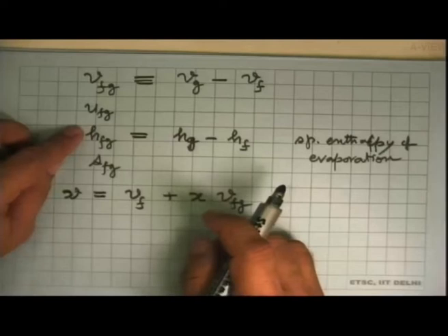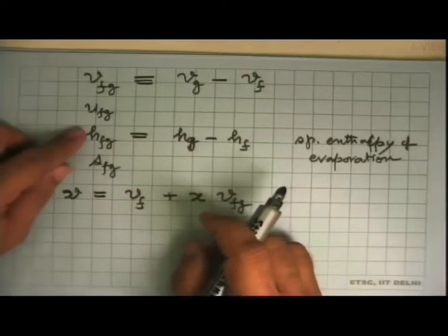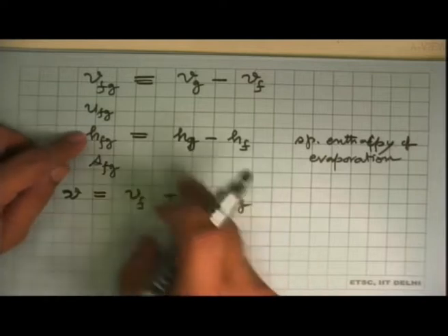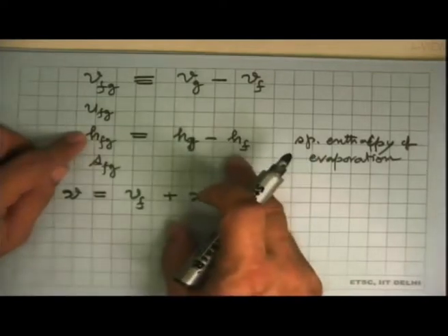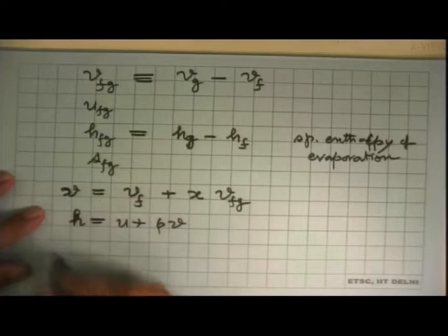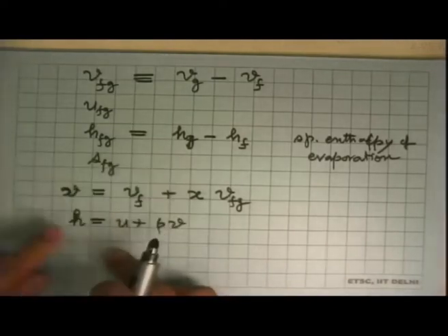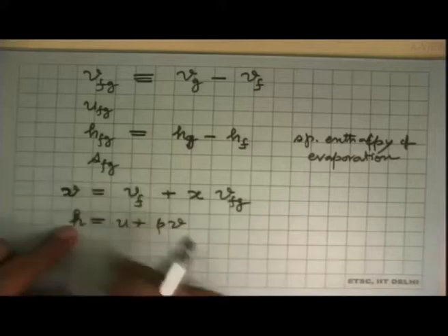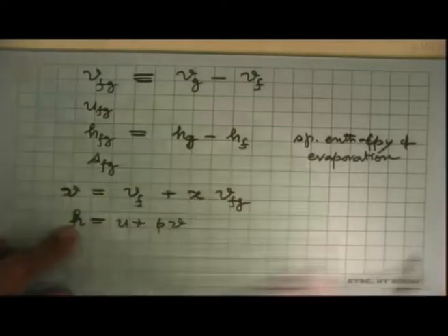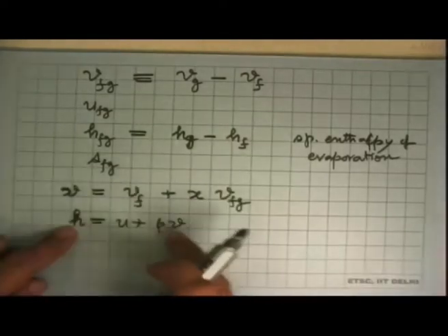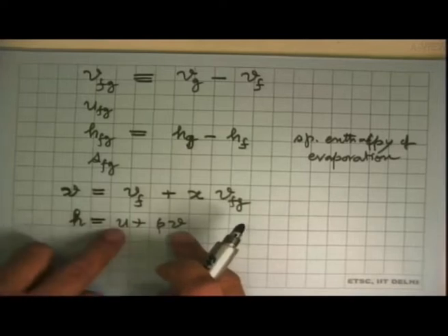Okay. In many cases, the tables will give values of these also, but there are many cases where they may not give these values. And the reason would be that if you want that, we can just calculate it from the values of Hf and Hg. That's what is there. And in the tables, this property relation also is always true. H is equal to U plus PV, the property relation we have already seen. So in some cases, even U may not be given, only H would be given, because in many engineering applications, H is what is used very frequently. So you will find that there are no properties for U given. No need to panic. We know that H is given, P and V are given. From there we can calculate it.